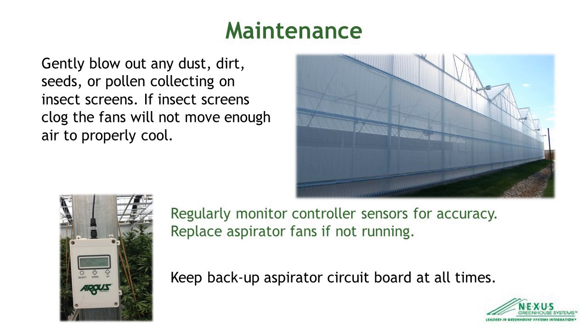Then moving on to the insect screens. Insect screens very rarely ever get clogged with insects. It's mostly dirt and other fine particles that you see in the environment. Say, for example, if you're in an agriculture environment, there's a lot of dust being kicked up, or next to a road, there's a lot of dust being kicked up. You'll have to go through and gently blow out the dust. Most often people do this with a backpack blower or a handheld leaf blower.